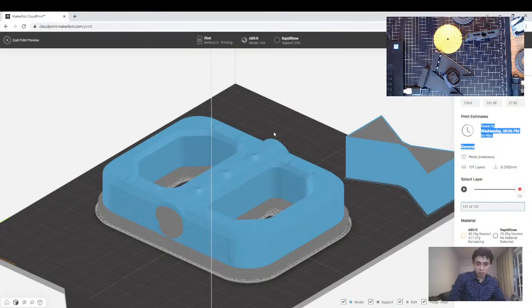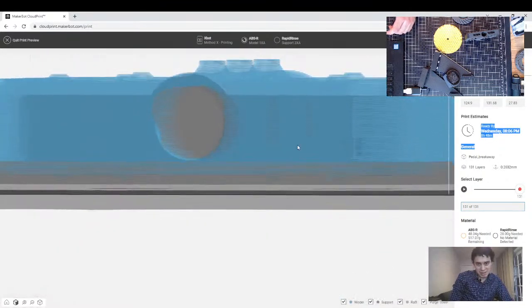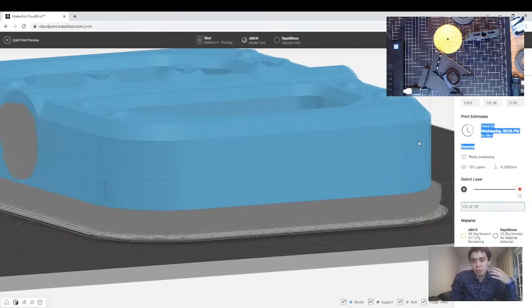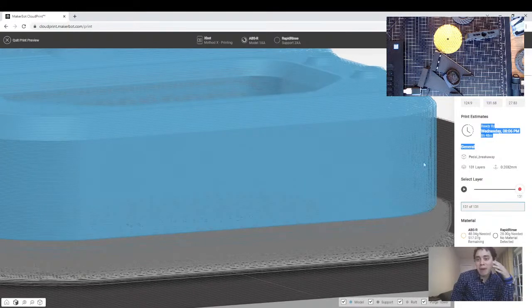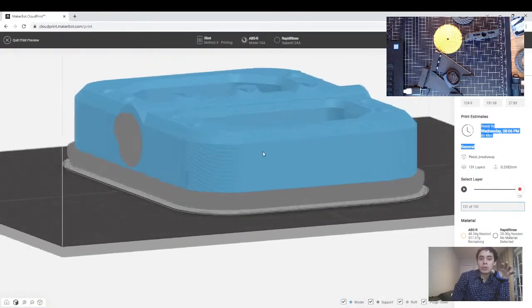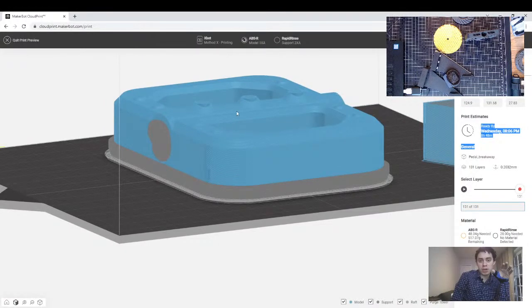That's a lot. And not only that, but now I can zoom in here and see that actually my layers, I mean, this is of course expected, but it's just so that we can double down on this idea, right? My layers are now properly aligned, perpendicular to the force that's being applied. So you can imagine how me stomping on the pedal, I'll be pushing in from the top down, and the layers are stacked up flat, perpendicular against that force.